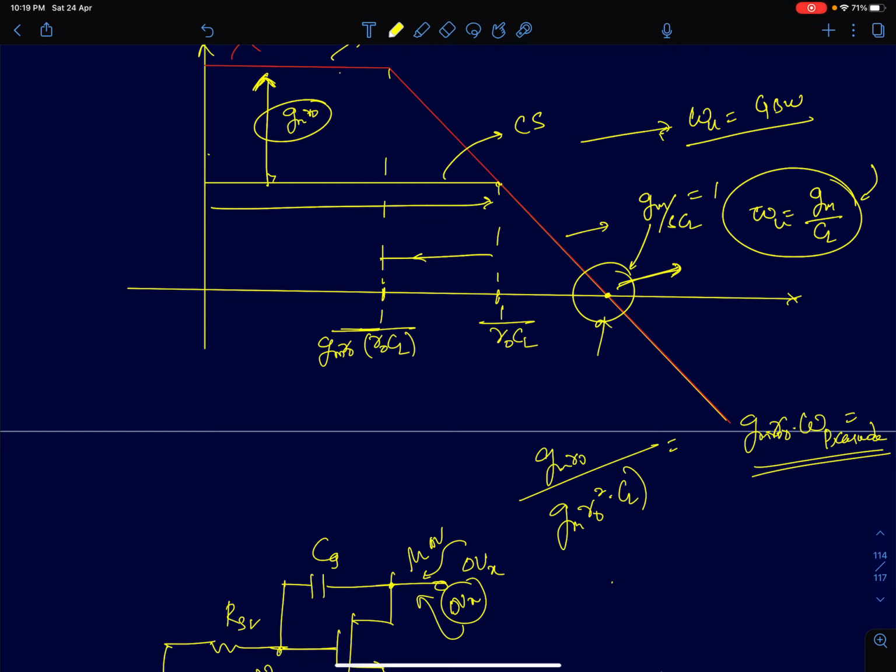So to summarize, when we were driving a resistive load, we saw that the DC gain was the same for common source and cascode. The benefit there came in terms of capacitance multiplication. The input pole, because of the source resistance, could be pushed away to higher frequency in a cascode amplifier. That was the benefit there. Whereas when you are driving a capacitive load with no resistive component, which means RL is infinity, the benefit is in DC gain.